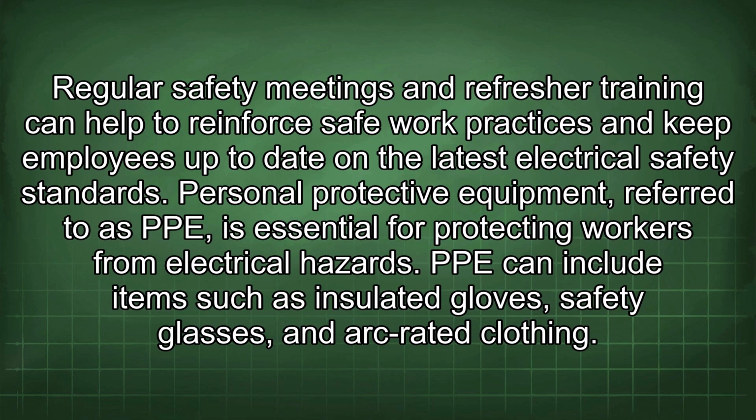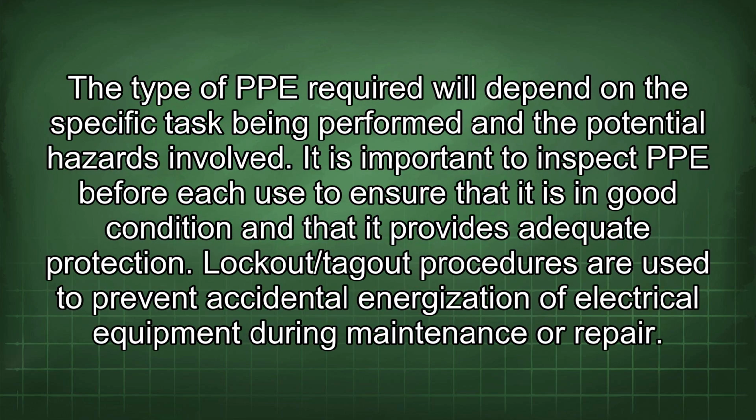Personal protective equipment, referred to as PPE, is essential for protecting workers from electrical hazards. PPE can include items such as insulated gloves, safety glasses, and arc-rated clothing. The type of PPE required will depend on the specific task being performed and the potential hazards involved. It is important to inspect PPE before each use to ensure that it is in good condition and that it